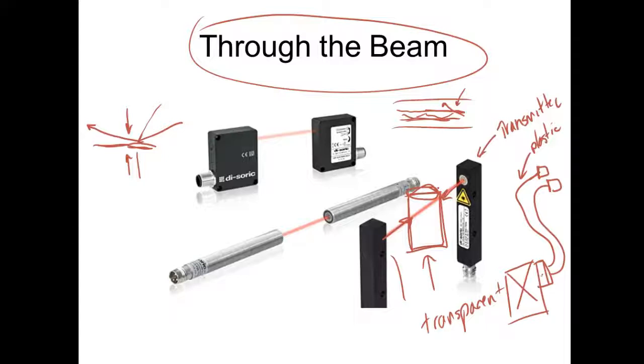So what that means is these sensors are going to require at least 3 wires. We're going to have to put it across, and these are DC sensors. Normally your sensors, by the way, are DC. Your solid state sensors, excuse me. But they do have some AC that we'll look at. And then you have one wire you'd hook your positive DC up to, one you'd hook your negative DC up to, and then one you'd hook your signal to. But it's still 3 wires. Eventually, they're going to have to come out.